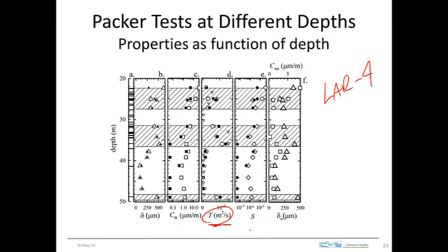Here's transmissivity and storativity. These are the common properties, and we can see that they vary by quite a lot as a function of depth along the borehole. There are three main permeable intervals. This upper permeable interval here, all the three intervals are hatched. So this interval here, and then this lower interval. And they're identified with these multiple packer tests that give different properties.